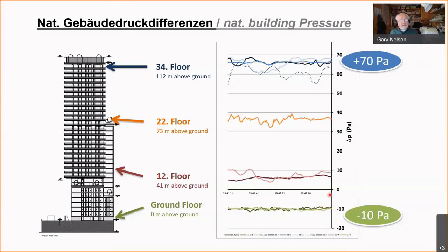And this is the zero pressure measurement over a 2-minute period of time. And these are also 1-second averages. And you can see, you really want to measure the pressure at the bottom of the building. You don't want to be measuring and doing calculations on the pressure at the top of the building. And then we ensure that there aren't pressure differences between the top and the bottom of the building by measuring internal pressures and adjusting fans so that the building is in the single zone condition.